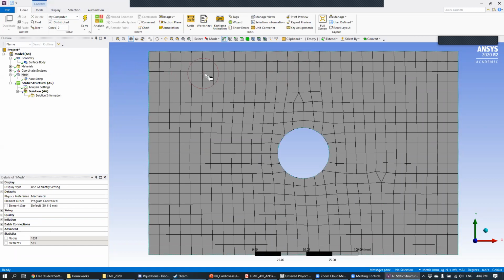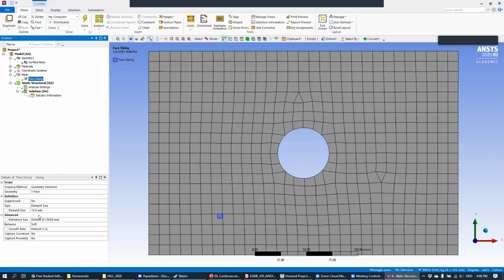Well, what was the step after that? You just resized one of the squares? Right. Under the sizing option here, you want to click the face to select it. Normally this geometry is yellow. So click geometry, click the face right here, and then click apply. That'll select this face, which tells us we want to change the mesh settings on this particular face. Then we want to change the size of the elements right here.